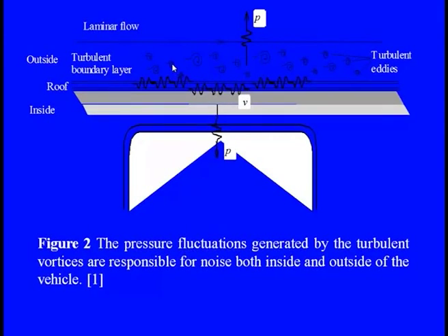The entire fluid flow across the train, or any vehicle, is a combination of turbulent and laminar flow, because somewhere you see steady flows according to streamline conditions, but somewhere, because of pressure fluctuations in the air and surface interactions, turbulent boundary layers are created. We can apply this theory to formulate how much turbulence there is according to the speed and air velocity.